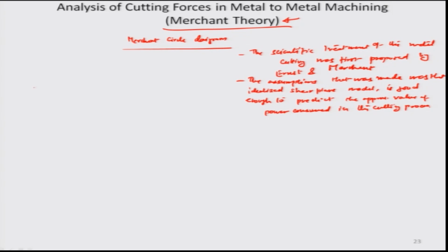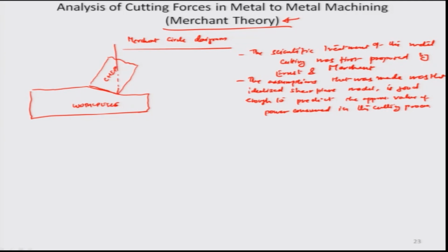And so let us now look at how the chipping process is happening here. Let us say this is the workpiece that we are considering, and there is some kind of a chip formulation which takes place somewhere here. This chip actually comes out from this particular plane, and you have the chip traveling in this particular direction. So this is actually the chip, okay, the workpiece from which the chipping process has happened. So you also have the tool component here, which is actually at an angle alpha, the rake angle with respect to the chip surface.